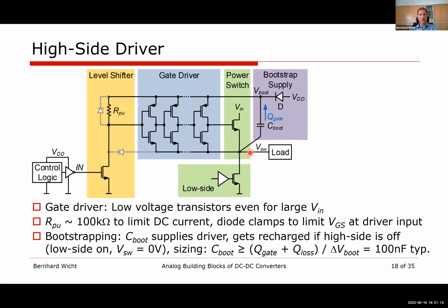So there is a lot of effort in the layout, also in the mounting, and how to build your PCB, right? All these things that you're mentioning. There's no magic. We need to keep very short and small loops. Plus, one technique on the circuit side is blanking. In the very first moment, you blank your sensing circuits so that they do not get disturbed by the ringing. That's the quick answer I can give in this moment.